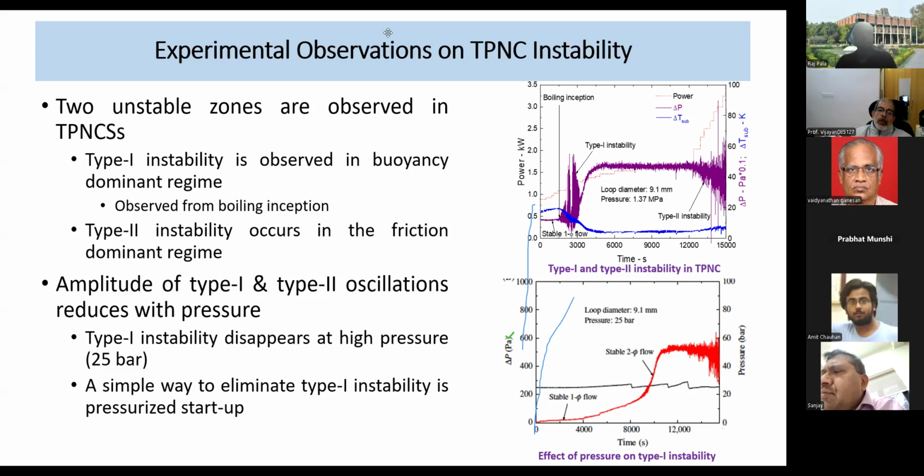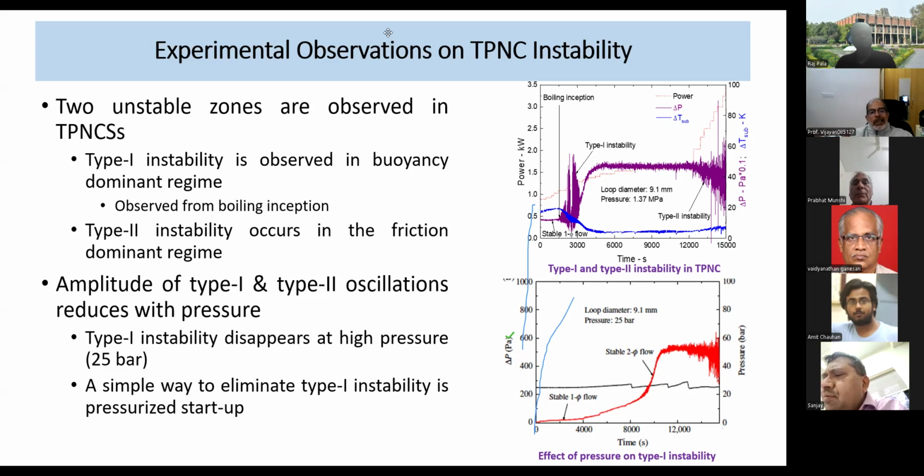Rolls-Royce is developing a 300 megawatt electric natural circulation based one. And they are claiming that it is 18 crore per megawatt electric. So, which is still higher than our 700 megawatt electric, but it is a 300 megawatt reactor. So if you increase our power rating, then the cost per megawatt comes down.